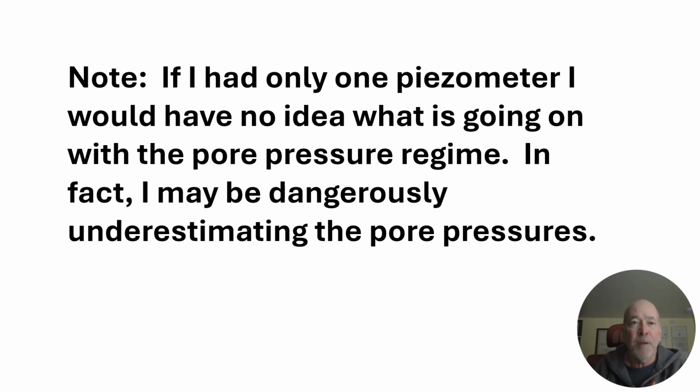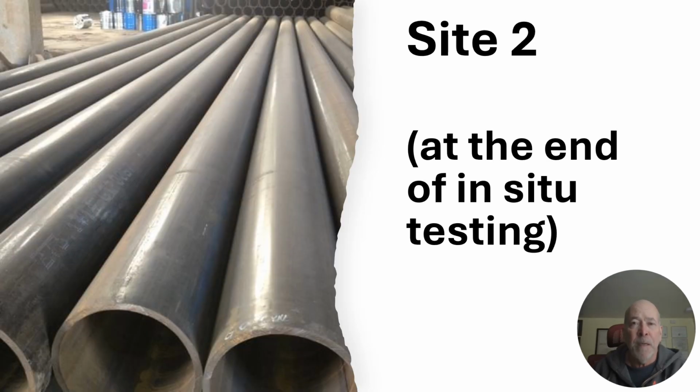So, if I only had one piezometer, I would have had no idea what's going on with the pore pressure regime. And in fact, I may be dangerously underestimating the pore pressures if I thought something was hydrostatic and I only had one point. The actual water table might be a lot shallower than I had assumed, especially if I just put in that last piezometer. I would think that there's practically no phreatic surface, no water table in there. So that could be very dangerous, right?